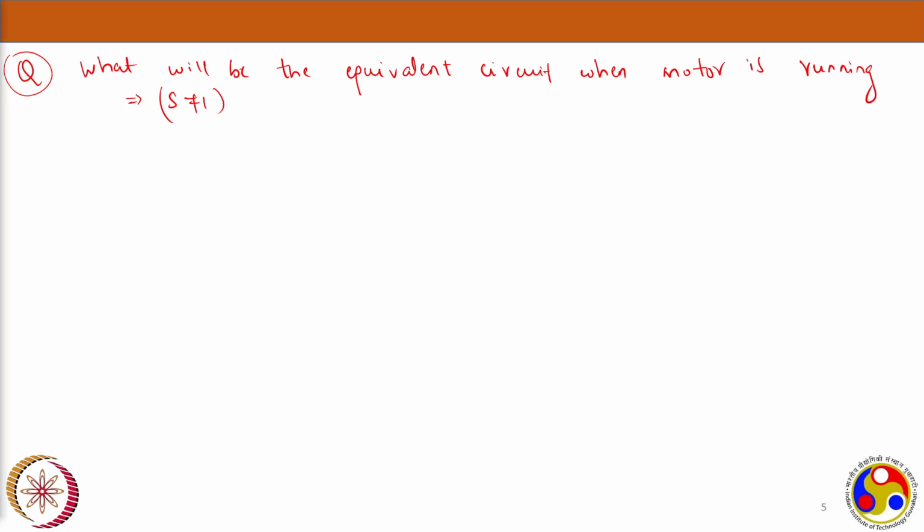This is the important discussion, and that is the actual induction machine equivalent circuit we want to look at. Now the stator side remains the same. There is nothing much difference you would see in the stator because there are R1, X1, XM, V1 you are giving, E1 will be induced, everything is the same. And the rotor side, because of this running condition, your parameters and quantities are not the same anymore.